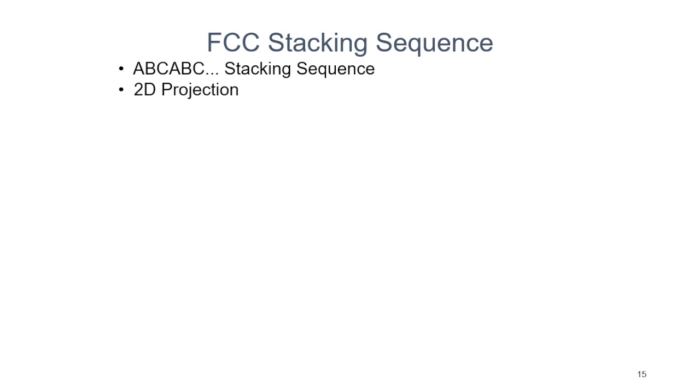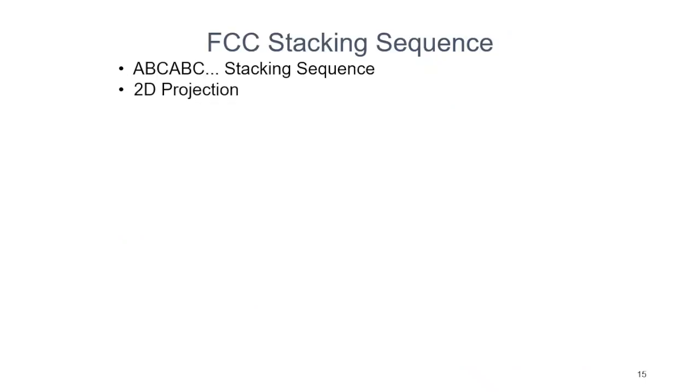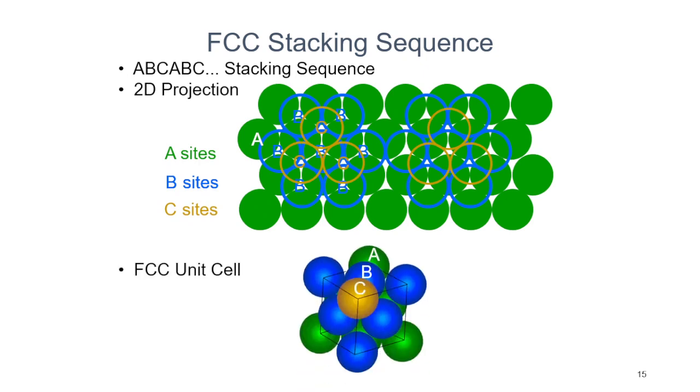Before that, let's have a look at the stacking sequence. We are only discussing one unit cell over here. But what if we look at the bigger picture? When we are looking at an image under a microscope, we will not be looking at just one unit cell. One unit cell will be too small to look at. We will be looking at a bunch of unit cells, all very small and crowded together. The only way we can tell one structure from another, though it is difficult, is by finding its stacking sequence. So for the FCC structure, this is usually how it is stacked.